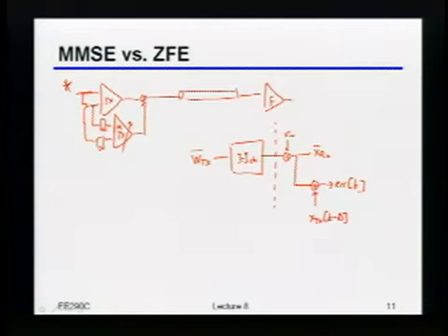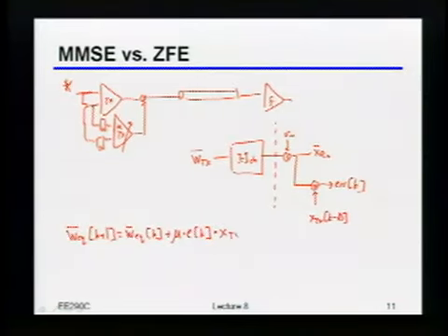So if we write this out, using the notation we had before, the update equation we're going to have to use in this case is like before: we take the previous equalizer coefficients and add some update to them. But this time, we take the error signal, which is measured relative to the received data, and the only thing we can really correlate it against is the ideal received data. In other words, we have to take the analog error and correlate it with the received digital value, whereas before we were taking the analog error and correlating it with the analog input into the equalizer.